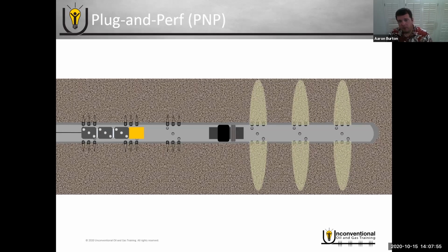So just to kind of give you a point of reference, at least currently, the most I've heard of an operator running perforation guns in one stage has been 20 clusters per stage in a single wireline run. And even that is still not that common. Like I said, it's still averaging between 6 to 12 per stage.